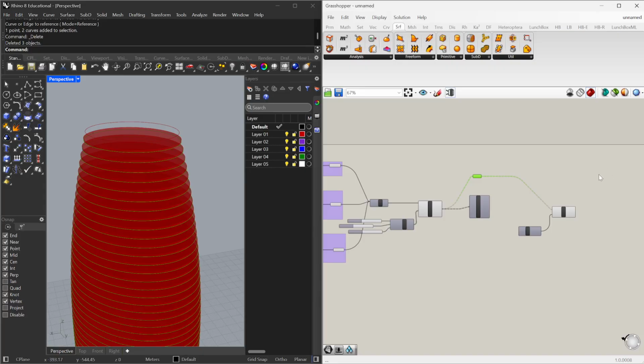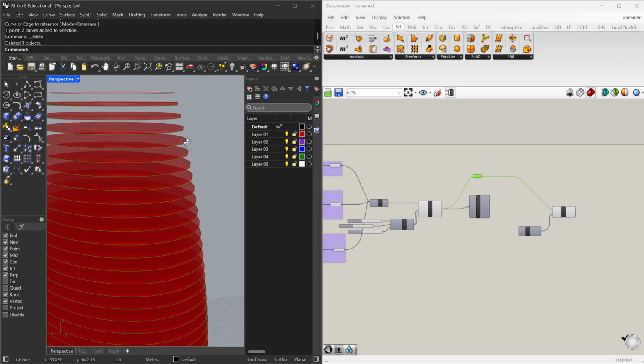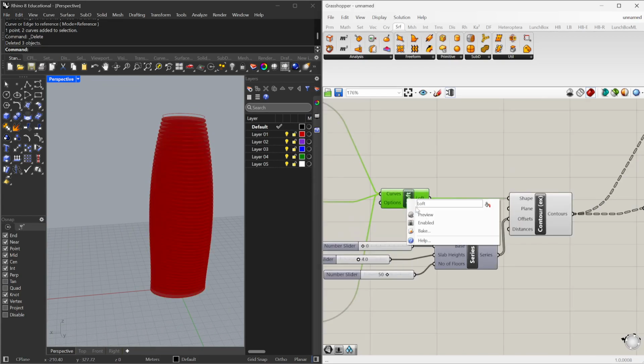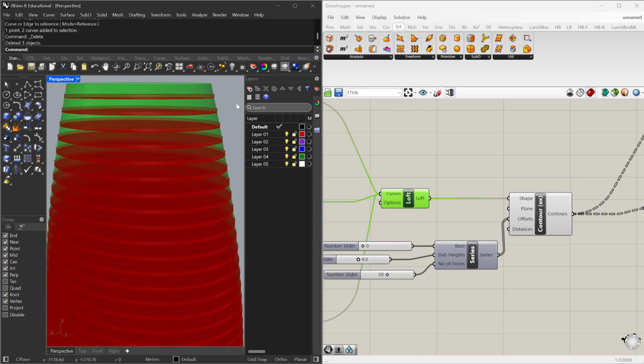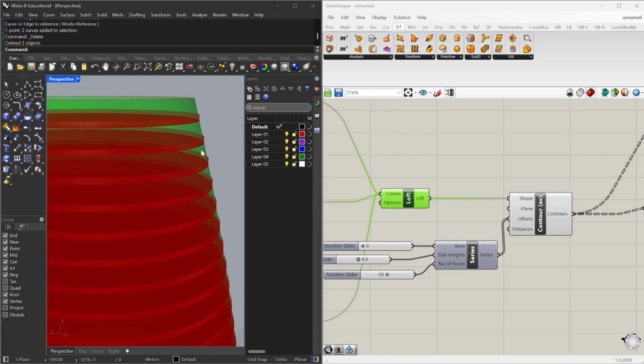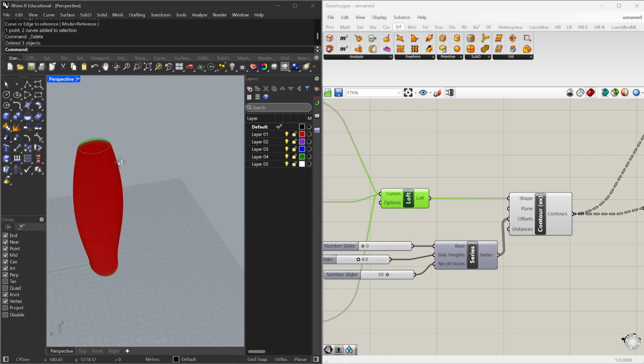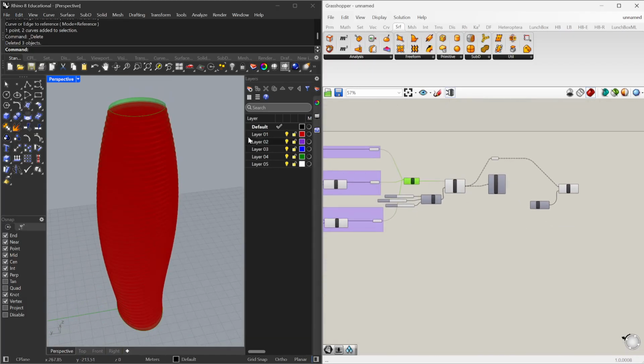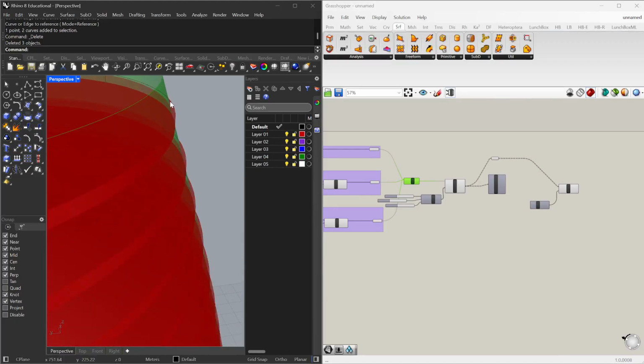Go ahead. Yeah, so what you'll see happen, because of the way that our surfaces work, is that some of our surfaces will slightly overlap just because we're using a curved surface. There's a way that we could try to tackle that without going into too much complex detail. If we were creating a facade, we can just offset this surface ever so slightly, so we give ourselves a little bit of extra space.